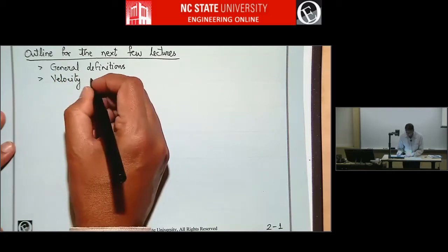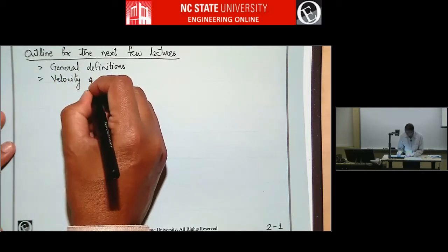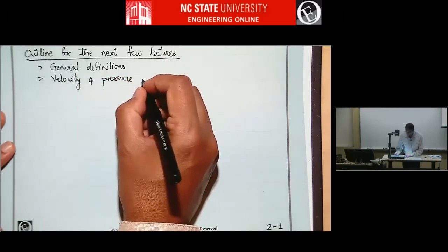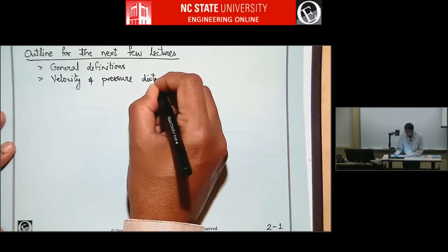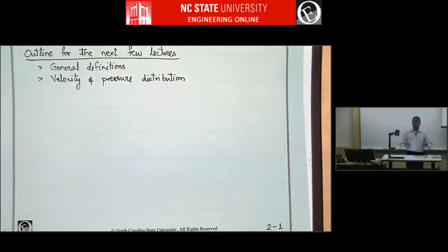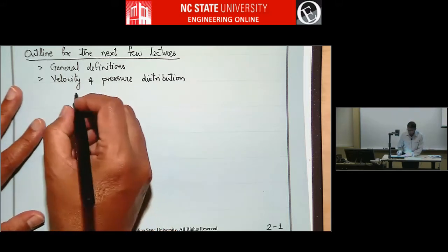So in some of these examples, we looked at velocity distributions, and we tried to say this is what the velocity distribution will do. It will support laminar flow, or it will create negative lift at the trailing edge and that sort of stuff. So velocity and pressure distributions are super important when it comes to airfoils. They tell a story about what the airfoil is doing.